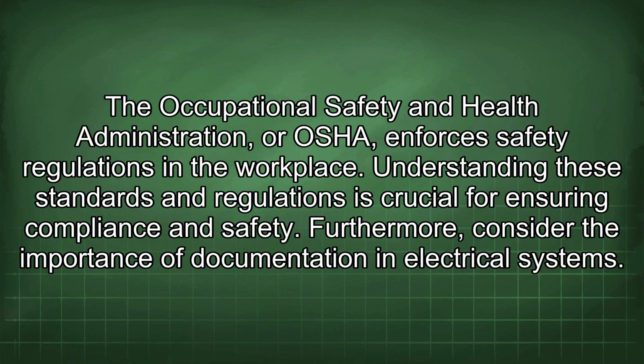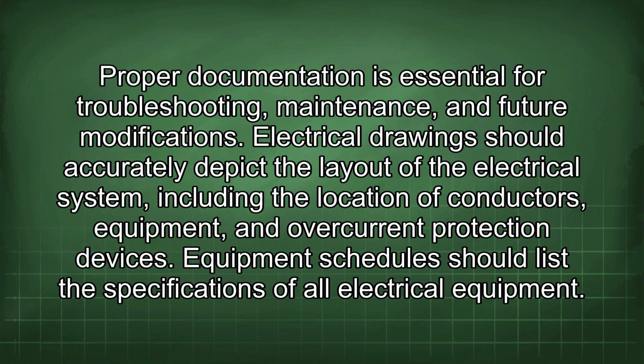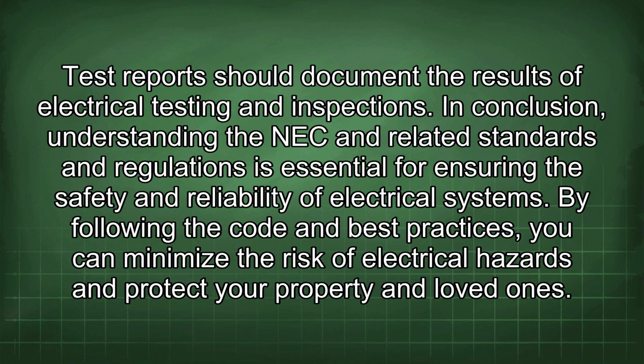Furthermore, consider the importance of documentation in electrical systems. Proper documentation is essential for troubleshooting, maintenance, and future modifications. The electrical drawing should accurately depict the layout of the electrical system, including the location of conductors, equipment, and overcurrent protection devices. Equipment schedules should list the specifications of all electrical equipment. Test reports should document the results of electrical testing and inspections.